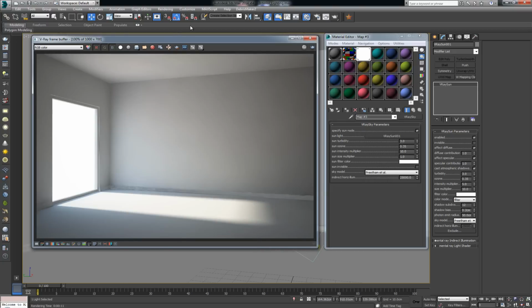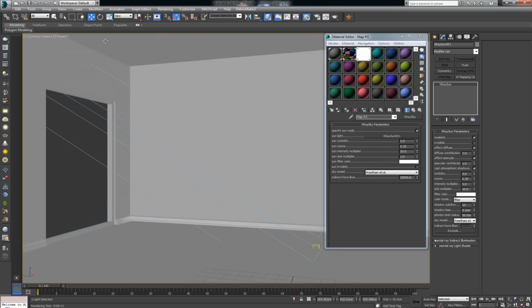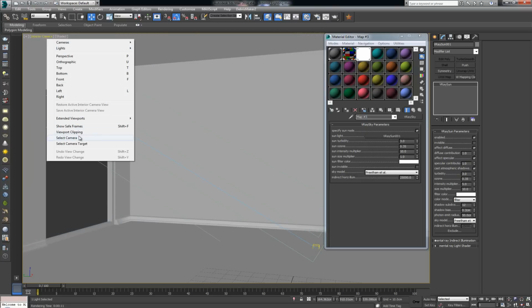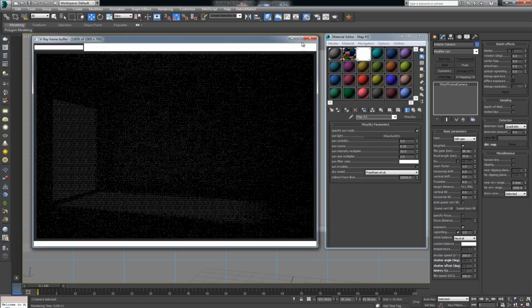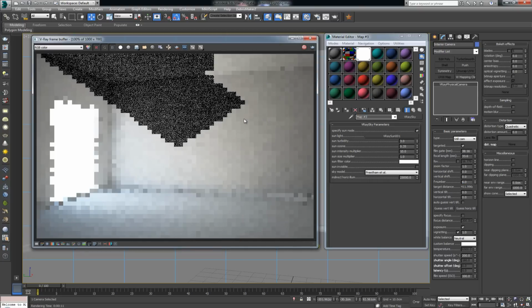So the next thing that I just want to add before we go over to explaining a few of the other issues that would arise with something like this is that if you want a lighter scene, you don't always have to go and change the sun multiplier or the environment multiplier. For example, you can go over in the camera settings, so select my camera, and over here I can just lower the F number to, like I previously said, 6. You would get a lighter scene now.